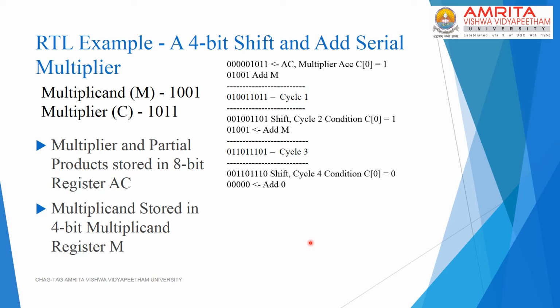And as a result of the shift, now the current multiplier bit that we are considering is a 0, which indicates that instead of adding the multiplicand, we have to add a 0 to the partial product. And the shifting process again is carried out by 1 bit position.